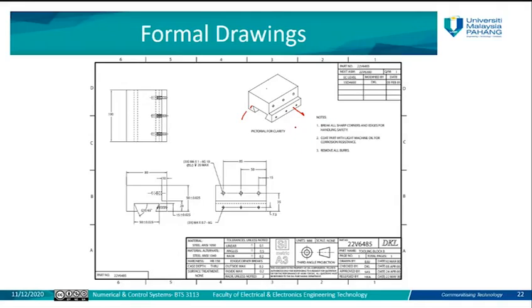So as a drawing reader, you need to extract all this information and convert it into values that will help to write a program. For example, in this view you can see there is 85, 50, 15, 35, all these dimensions. These dimensions represent, for example, a hole or a circle. There is a circle there, and a circle there. All these represent circles on the main shapes, for the right side view.